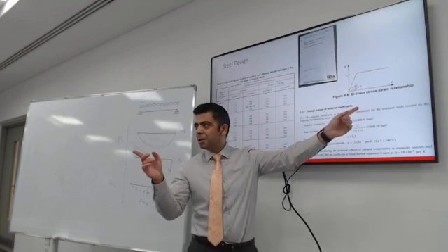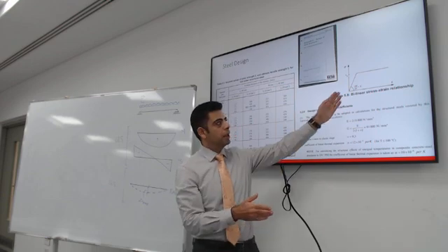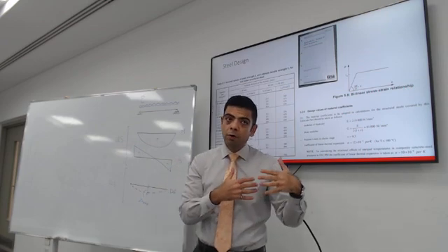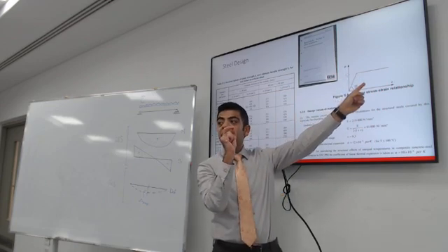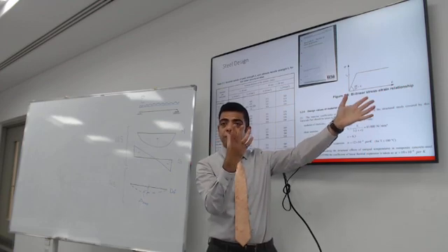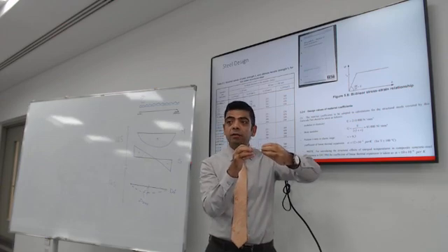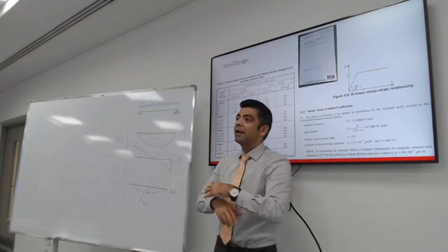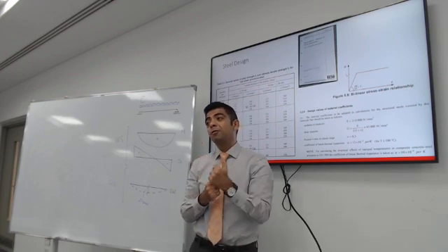Yes, that's the relationship between stress on a steel element and the strain or deformation. The relationship is linear. The more load you put on steel, the more it deforms in a linear way, until it hits a very specific number called the yield stress. After the yield stress, the steel cannot take any more load. It will just keep on deforming without having more resistance. So a class 1 section can achieve yield in the entire section. It depends on the geometry. I will show you the formulas.